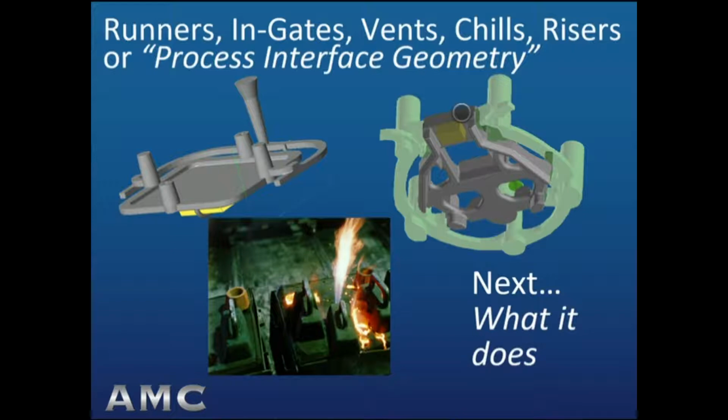And then at the center bottom, we see the venting of gases from a low alloy steel casting. In this case, we're looking at 2950 Fahrenheit as the pouring temperature, and the combustion gases from all of that temperature are very large, both in pressure and in volume, and need to be evacuated real specifically with a venting system designed in the right places and the right size.